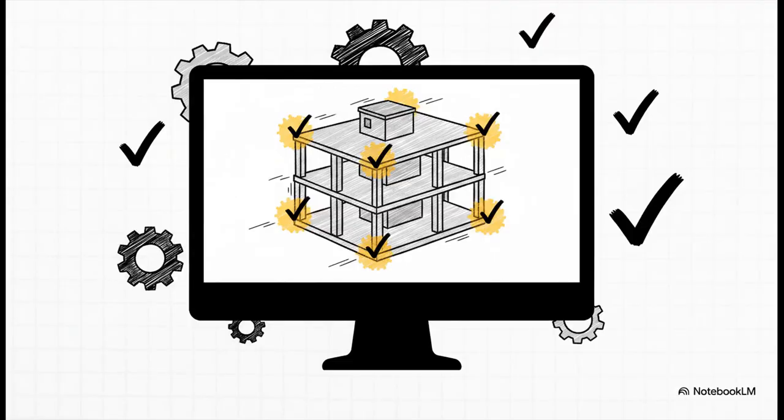To put this into practice, we just tell ETABS to process the design using the specified IS 456 standards. It runs these immense calculations across every single joint in our 3-story frame. And for our model, spoiler alert, every single component passed the ultimate capacity test. Our column-to-beam strength is exactly where it needs to be.